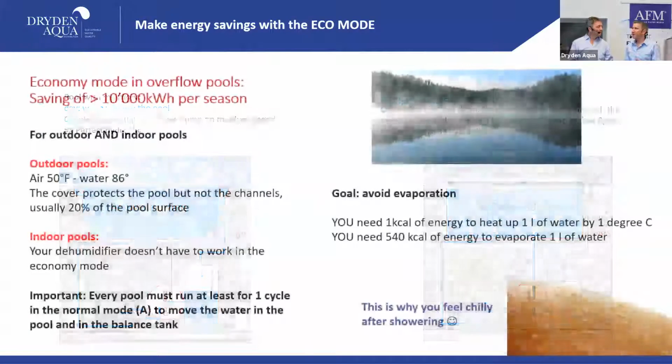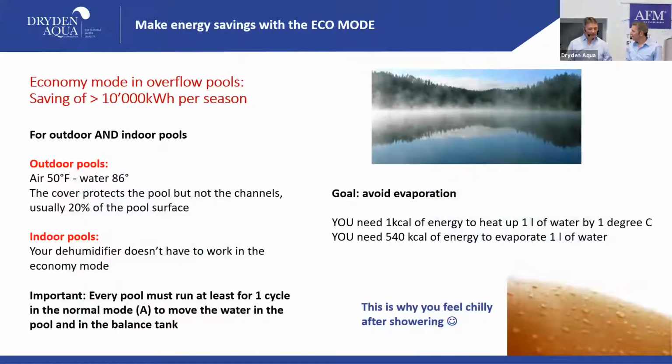So evaporation has a big impact on energy savings. Maybe I can quickly explain this. Evaporation you see up there, right? Now you have to understand, you only need 1 kilocalorie of energy to heat up 1 liter of water, that's 0.3 gallons, let's keep it in liters, by 1 degree, but you need 540 kilocalories to evaporate the water. I mean, really to change it from a liquid to a gas, and this is more than 500 times more, and that makes really the big difference.